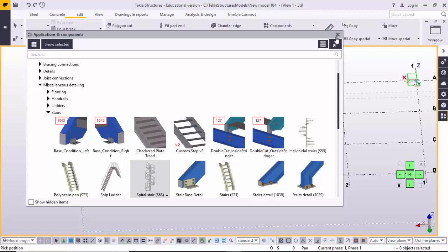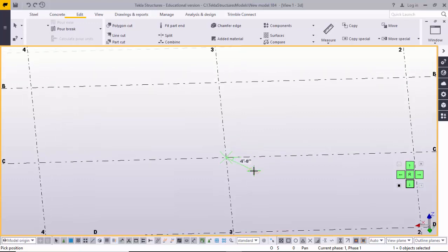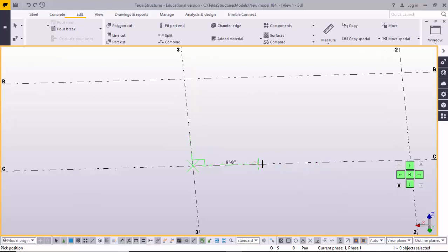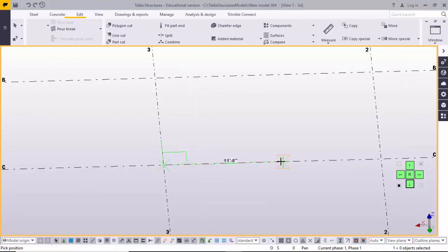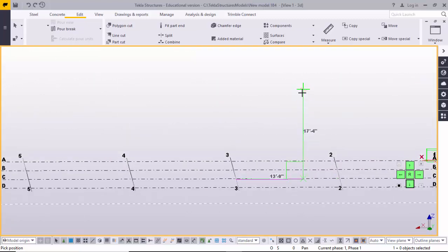Click on it, close it, and then pick the center point of this stair where required. Click on it and then give the direction, and click any position on this grid line. It indicates the entrance of the stair thread, the top position, any position on this grid line. After that, in the z direction perpendicularly, if you are not getting the perpendicular z direction, then click on Ortho, then you will get the perpendicular horizontal and vertical direction.